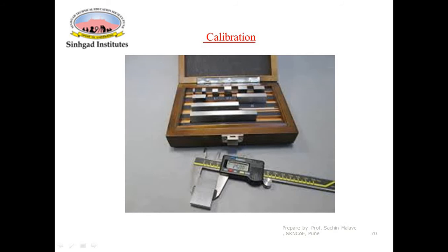Slip gauges are used as the standards, and out of the 6 faces of a slip gauge, two faces are highly polished. The opposite faces are perfectly parallel to one another, isn't it? So you can use that slip gauge. Hold the slip gauge between these two faces.